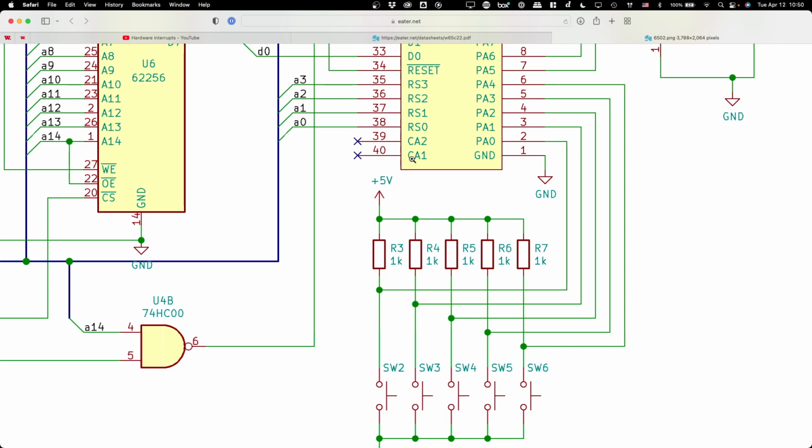You just said that we go back and read. We add an AND gate. You go back and read which one caused the interrupt. How does that work? There's a register inside the 6522 that if we read it, it will tell us what all 8 of the PA bits are. So we just read that address, that register, and we get, okay, here's what buttons were being pressed.